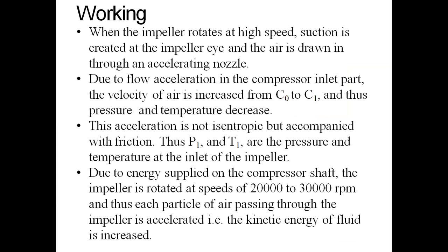Due to flow acceleration in the compressor inlet part, the velocity of air increases from C0 to C1 and thus pressure and temperature decrease. This acceleration is not isentropic but accompanied with friction. Thus, P1 and T1 are the pressure and temperature at the inlet of the impeller.